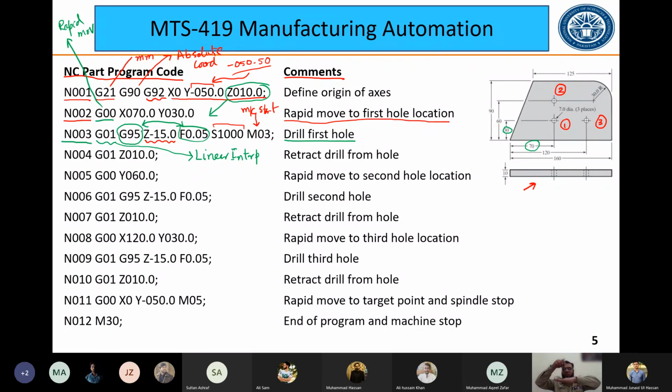So we were at the top of our workpiece, and now the drill bit is going to go like this into our workpiece and drill a hole for us, and it is going to go to Z minus 15, where I'm touching my right hand finger at the moment.